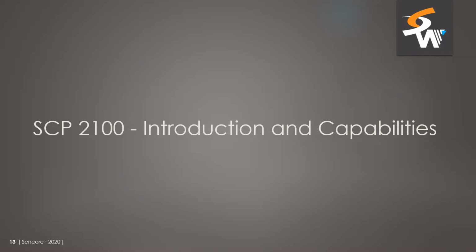Well, we can't just take that single service out of there and send that back, because since it has been statistically multiplexed, the video bitrate could fluctuate quite a lot depending on how they have their multiplexer set up. So if we just pull out that individual service and send that on with restamped PCRs, now we have a wildly varying transport rate on the output.